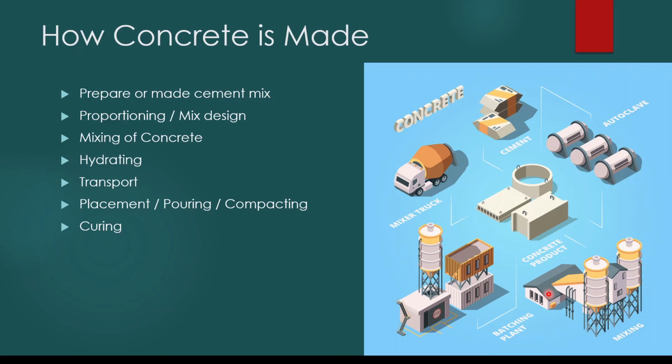With that, we have to do the curing. We should not let the surface of the concrete dry, and we have to maintain moisture on the surface of the concrete to complete the hydration process, which is the reaction between water and cement. That affects many factors, durability and other concerns. So you may refer to the video we have developed on the curing of concrete. But anyway, we have to do the curing for at least 7 days. With that, we complete the process of producing concrete.